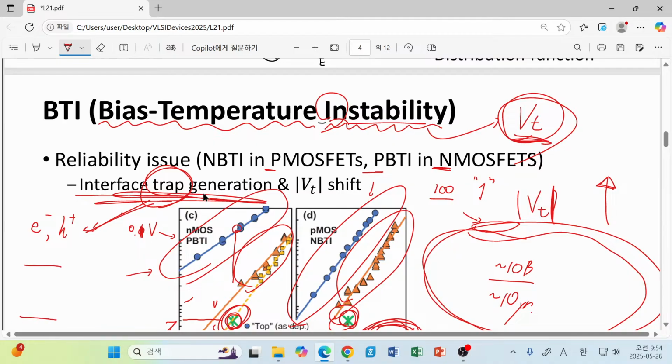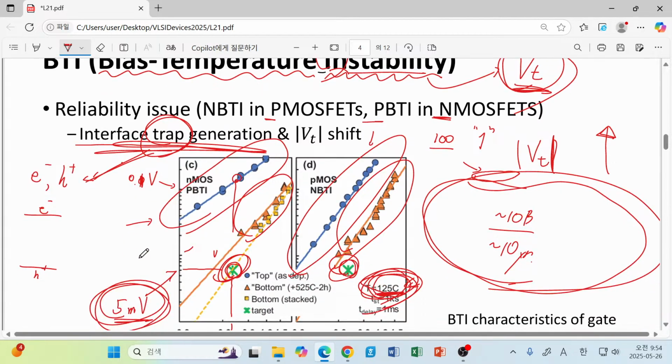In this context, we believe that if electrons are moving in the conduction band, they are free. If holes are moving in the valence band, then we say that they are free. Please note that this drawing is already assuming a vertical energy axis. So here we have the conduction band minimum and valence band maximum. And when we have electrons and holes there, then we think that they are free, just like a mouse hanging around on the floor.